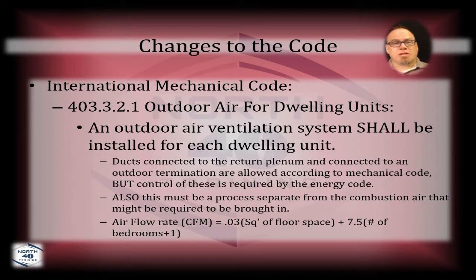And there's also a lot of inspectors that will allow you to put a return grill in the bottom of the door and the top of the door for the mechanical room. But what if there's not enough air coming into the rest of the house to draw from those other spaces to support the mechanical room? I'm not saying that this is the only way to think about this, but this is a way to think about it, and it might be worst case scenario, but you know as well as I do that if it's in code, eventually it could affect you in the way that you do your business. And so you do have to put some thought into these harder to plan for ordeals.